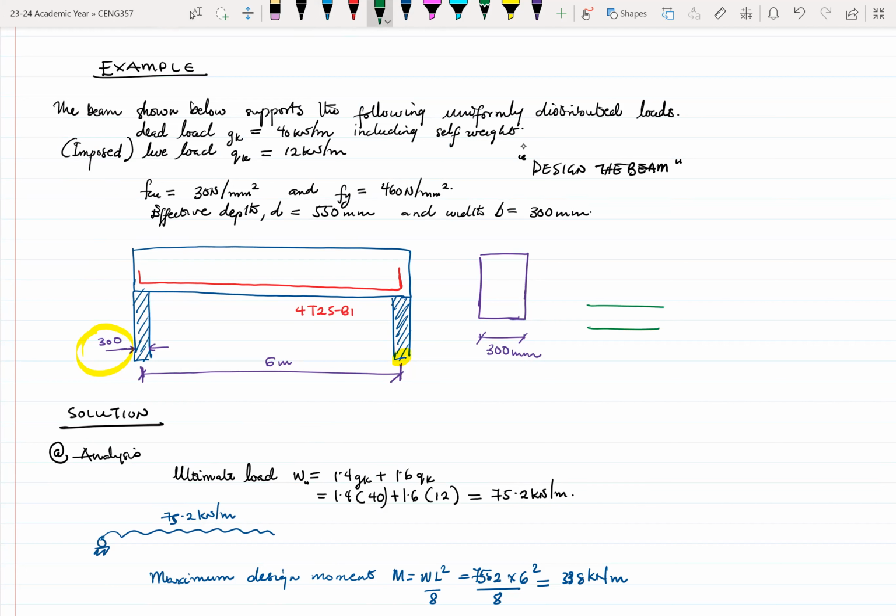Usually where the beams and the columns overlap, because you have the rebar from the beams going through, and also you have rebars from the columns coming through, there is a lot of congestion at that junction or that joint. Once there's a congestion of rebars, your concrete is likely not to be placed properly over there.